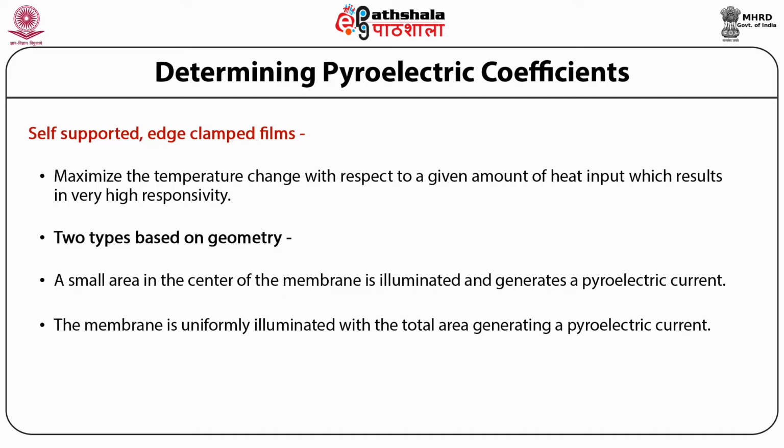The important thing to consider here is the mechanisms by which the heat is transferred through them. Depending on the material of the self-supported film, any one of these may dominate. First is thermal conduction through the self-supported film. Second, radiative transfer to the environment from the detector area or from the whole film. Third is heat transfer to the gas surrounding the sample.